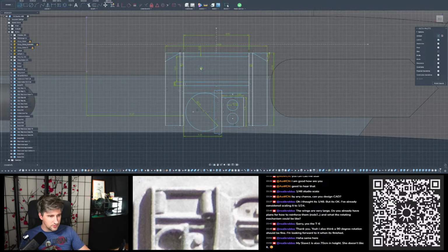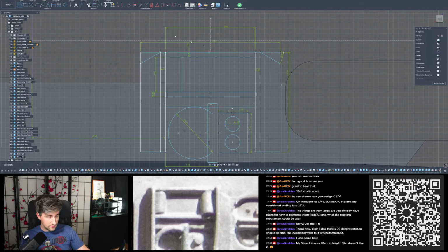Yeah, probably just extrude those as well and then put fillets on top of it so that it's only round on the top surface and not on the bottom, which is better for printability, and you will not see it on the finished model.